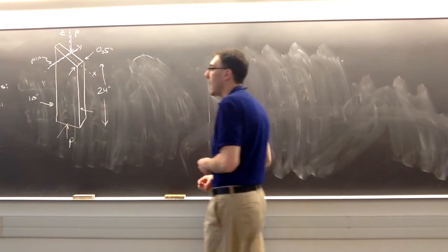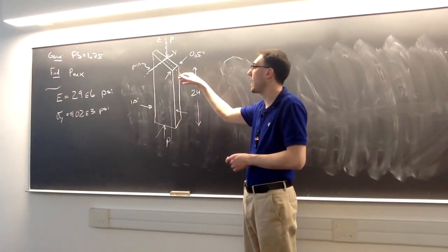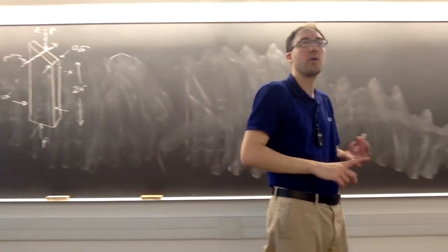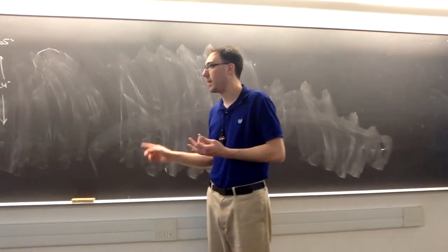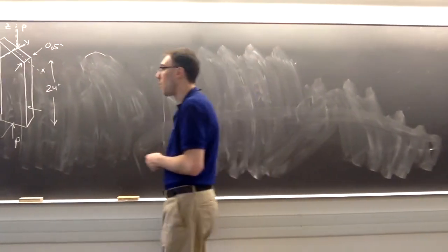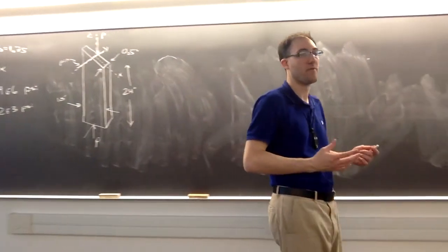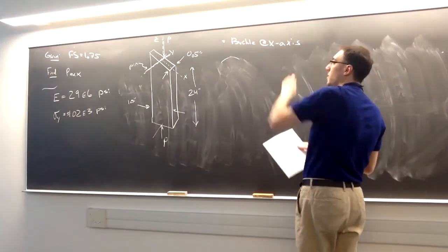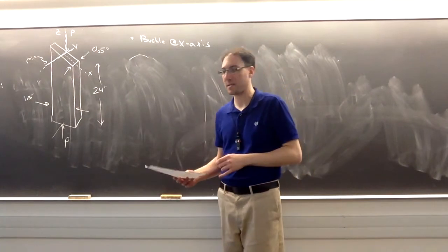So what we want to look at is how much does it take to buckle around x, how much does it take to buckle around y. We also have to consider, is it going to buckle at all, or is it just going to crush, and see which one happens first. Or at least test our buckling stress versus the stress it would take to crush it. Okay, so I'll start to see what is the load it would take for it to buckle around that x-axis.